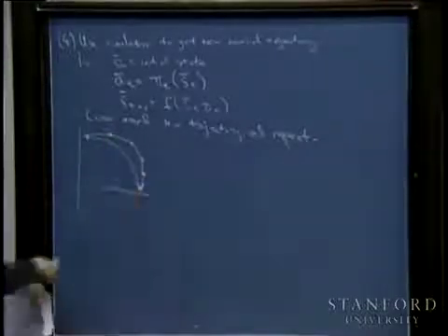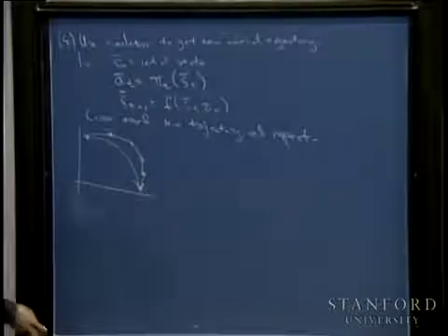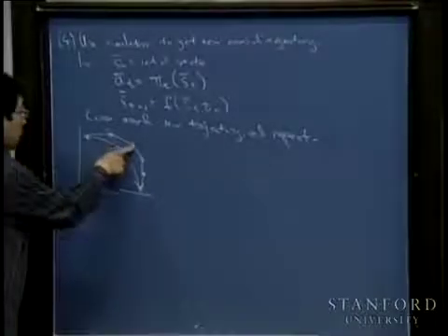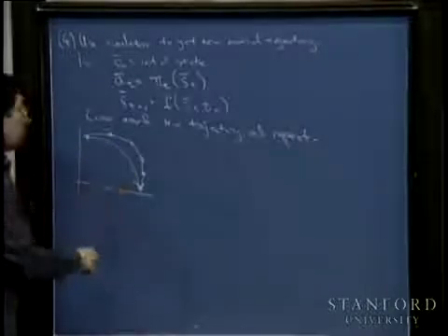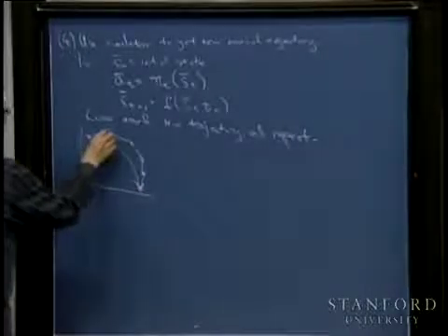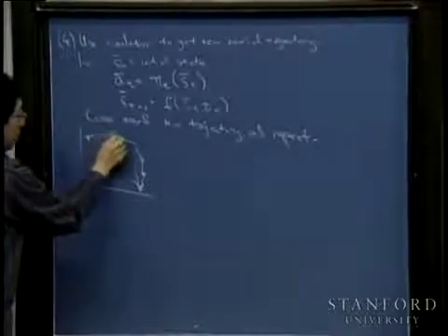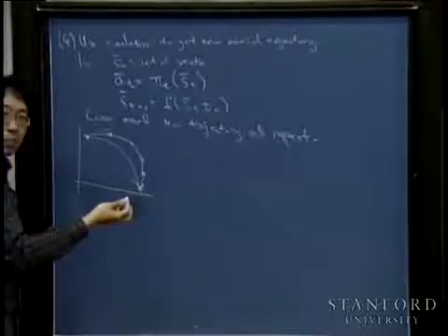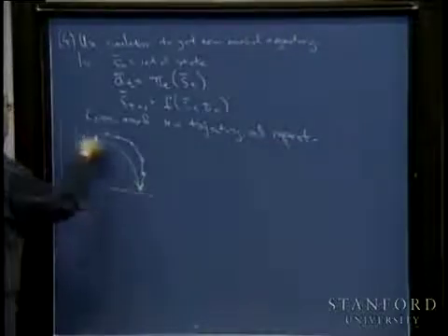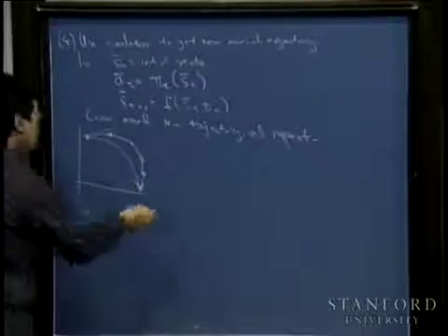Maybe your initial controller overshoots the turn, takes the turn wide. Right? But now you can use these points to linearize the simulator, to linearize even a very nonlinear simulator. And the idea is that maybe this state isn't such a bad approximation, that maybe a linearization approximation at the sequence of states will actually be reasonable, because your helicopter won't exactly be on the states, but it'll be close to the sequence of states at every time step.